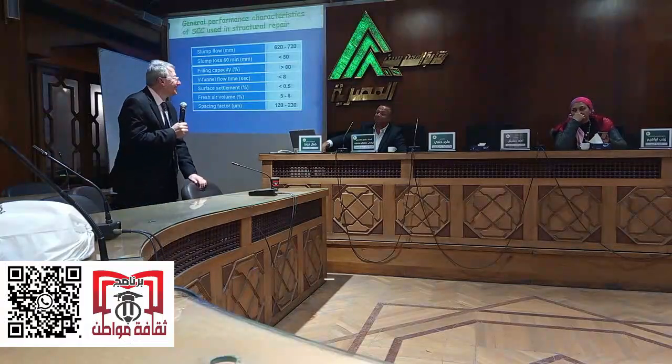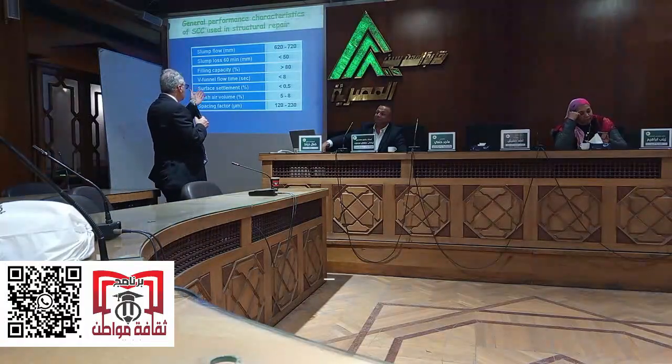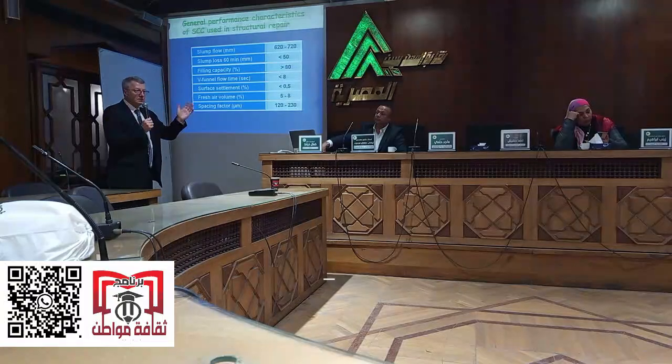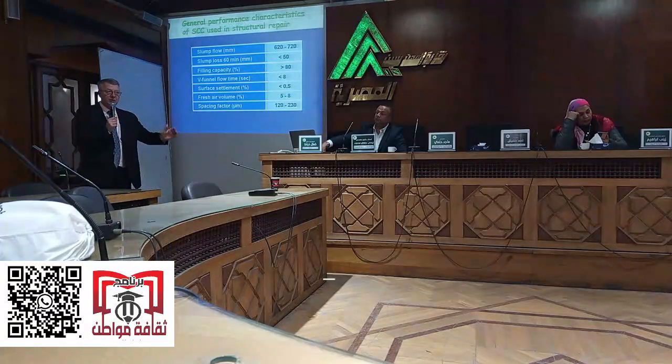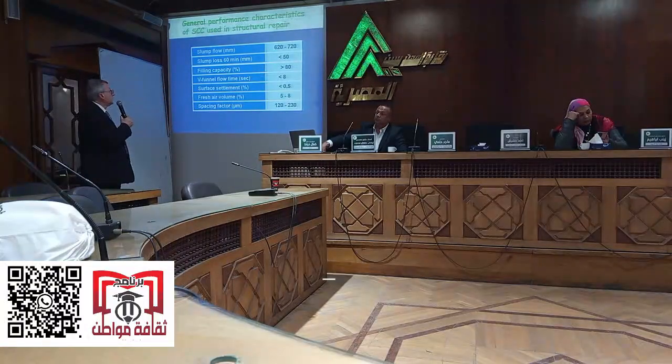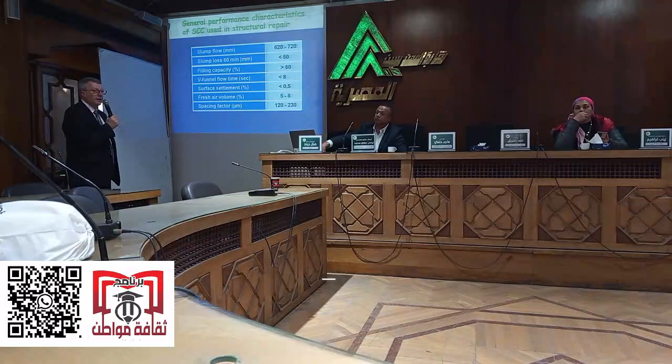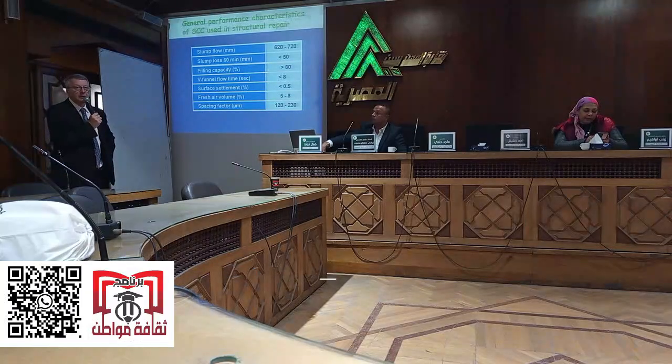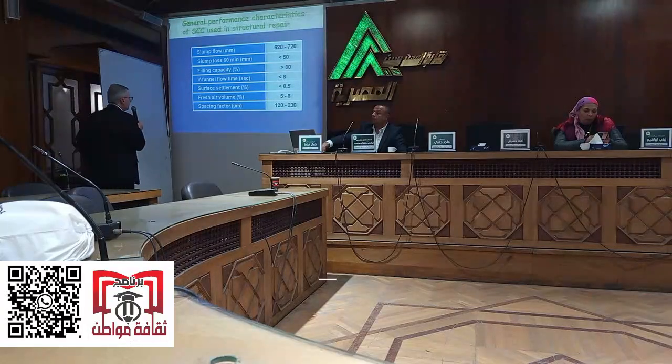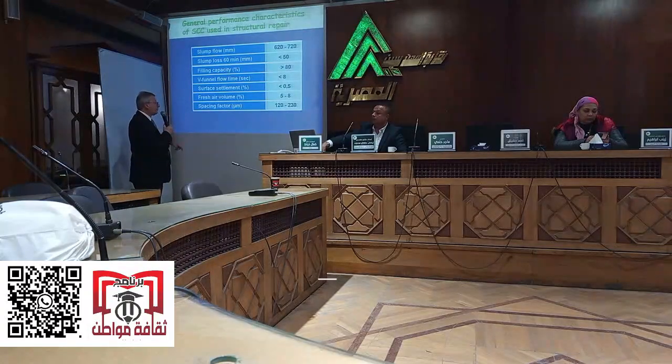Next. These are results from 40 repair sections that were done. The slump flow of the concrete varied between 620 and 720. After 60 minutes, we lost less than 50 mm of slump flow. The surface settlement was always less than 5%, and the fresh air content was 5 to 8%.